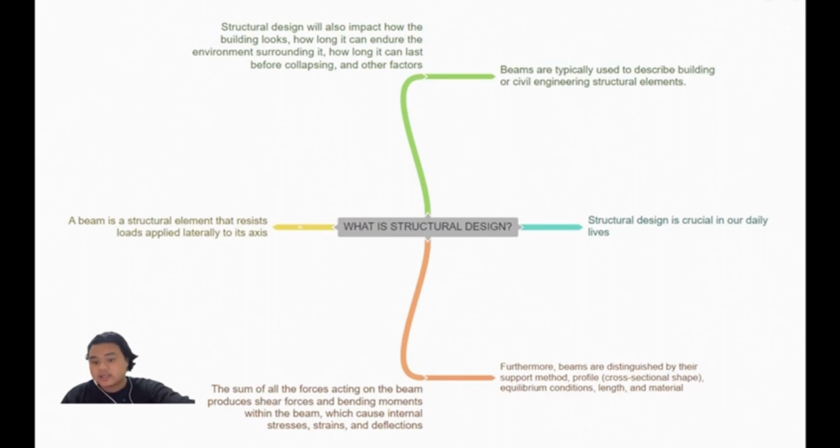Besides that, we chose R60 as our fire resistance standard to ensure that our double-story building can last longer and delay the spread of fire throughout the building in the event of a fire. We just calculated our Gk and Qk and we decided to use Gk of 4.69 and Qk of 1.63.